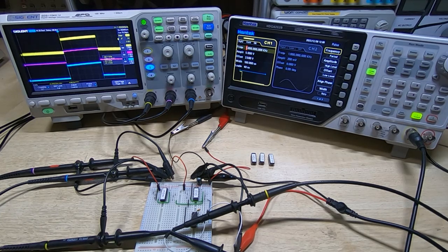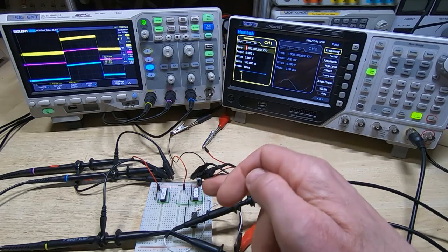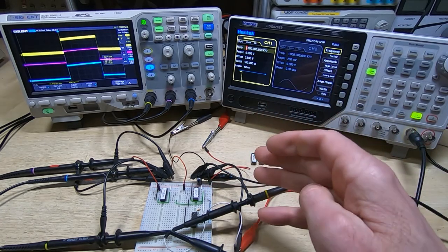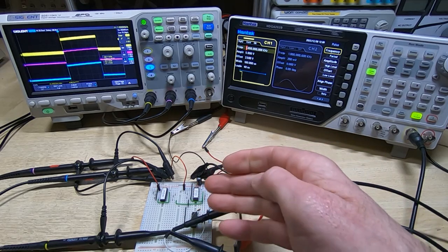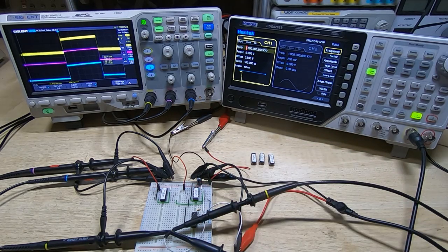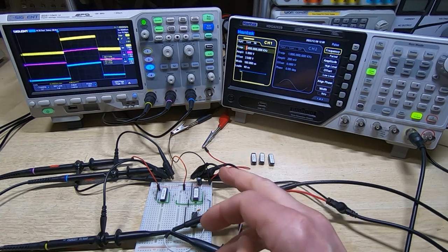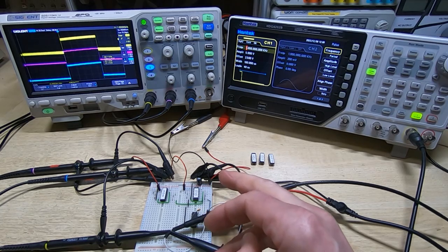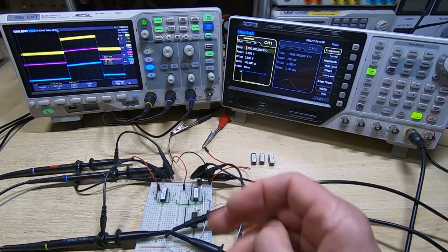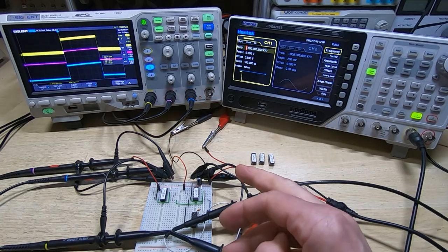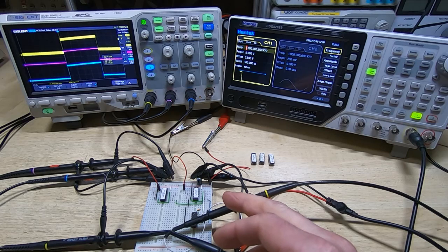So the first one was the use of a breadboard to demonstrate this sort of thing, and the comment said that it's not a valid way of doing this because the breadboard itself will introduce delays. Well, no, it won't. It's not really the issue with breadboards. The problem with breadboards is the capacitance and the contact resistance, and yes, it can cause issues, but not in a circuit like this.